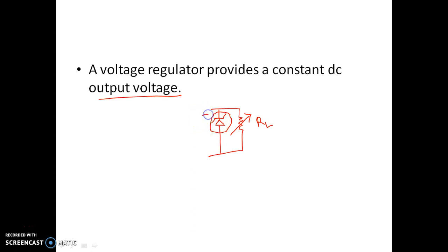So in reverse bias, suppose it is given what amount of DC voltage the Zener diode will produce in the breakdown region. Suppose this is in the specification sheet, it is given as Vz. Now although the load resistance will vary, because of the Zener diode in reverse bias, always across the RL resistor the voltage will be maintained as Vz, and this voltage depends on what type of Zener diode we are using. Different Zener diodes have different Vz. We can get this data from the specification sheet.